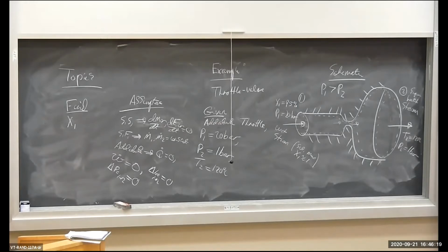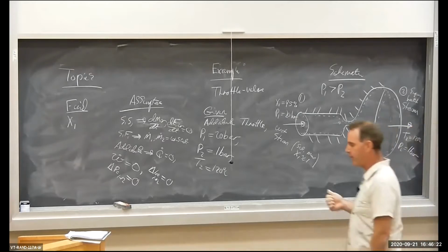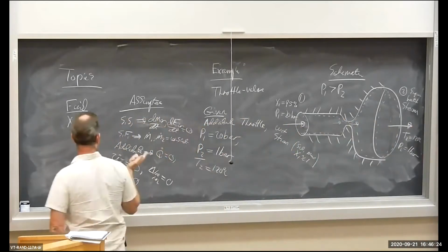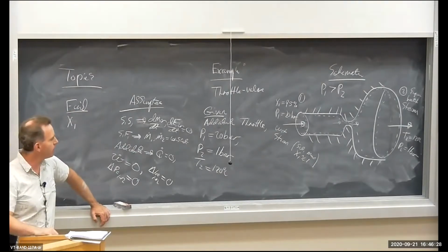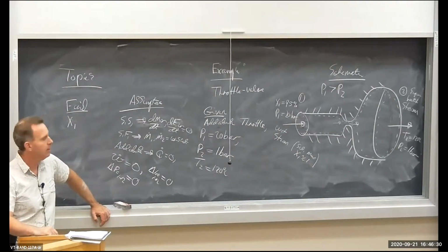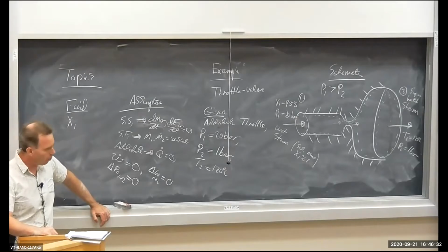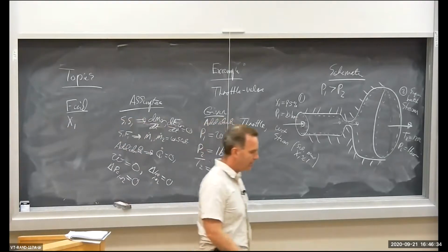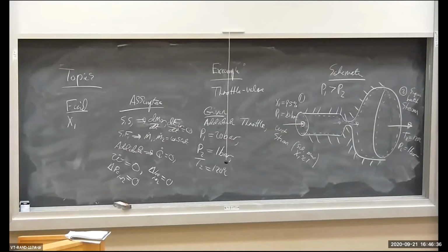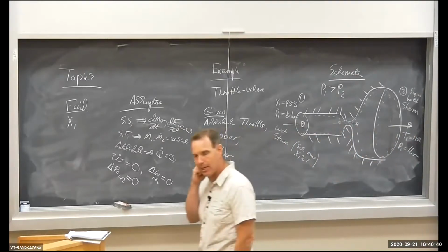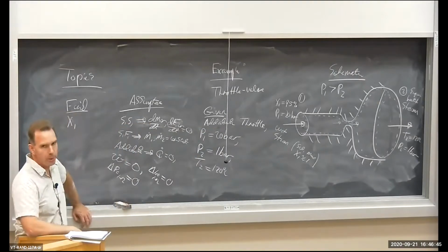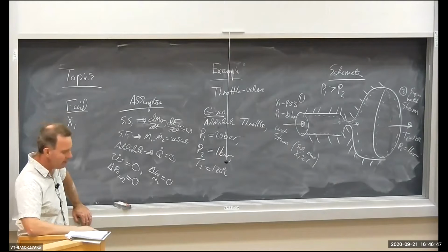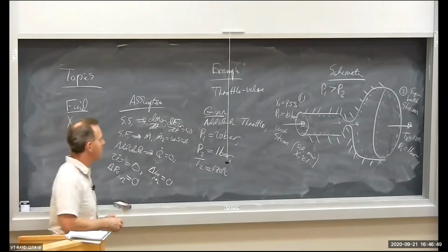So we learned how to apply the energy balance and mass balance to our first simple open flow device, a throttling valve. There's nothing going on in this valve. No heat transfer, no work. We're neglecting changes in kinetic and potential energy. Therefore, the energy balance tells us it's an isenthalpic, constant enthalpy process. H2 is equal to H1. Inlet enthalpy is equal to outlet enthalpy.